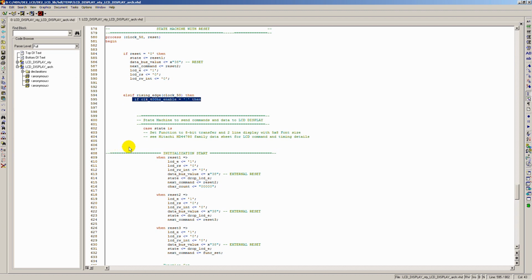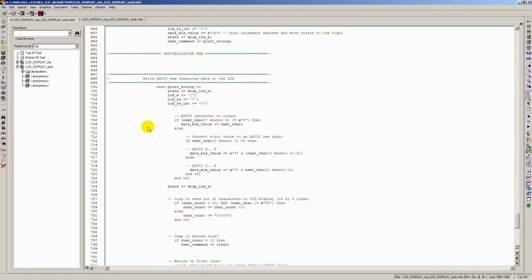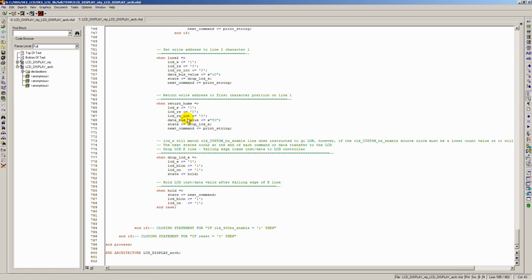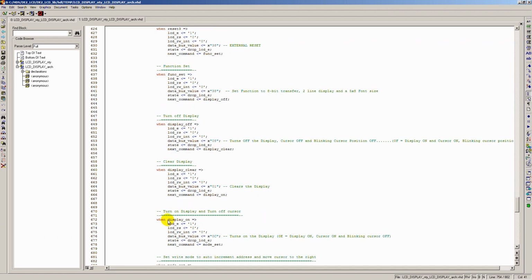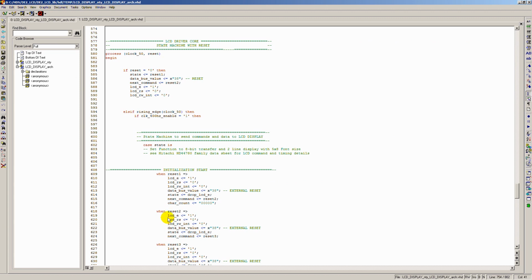It is pulsed high, and it drives that state once. And then what is it doing there? Well, our signal on our LCD enable is in a logic high state. And then in order to create the falling edge, it has to drive low. So it has to create another signal pulse to have the falling edge created.